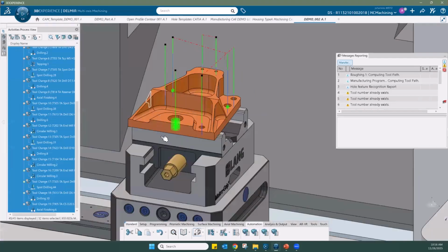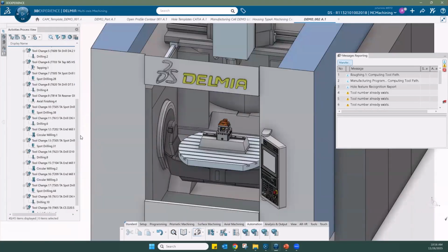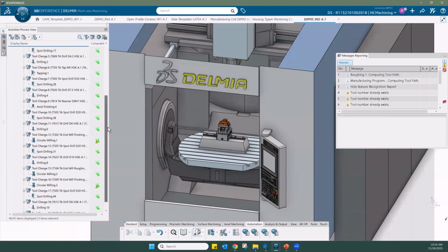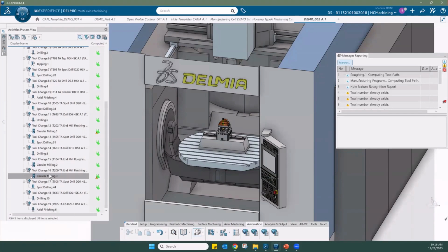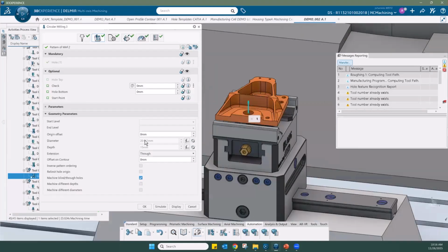Now you see all holes are defined. And now we want to check if everything is working correctly. For example, at first we have a tolerance hole H7, what I showed you at the beginning, and we compute it here directly in the mid tolerance.